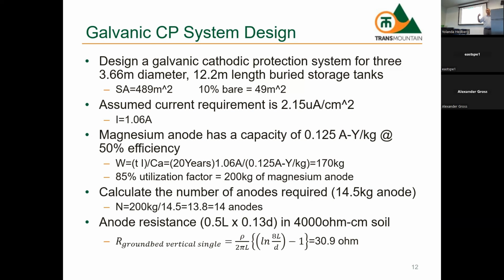Magnesium anodes, I already mentioned, you're not going to get more than 20 years out of them. That's because magnesium especially, but all metals, will self-consume. It has anodic sites and cathodic sites on the metal itself.